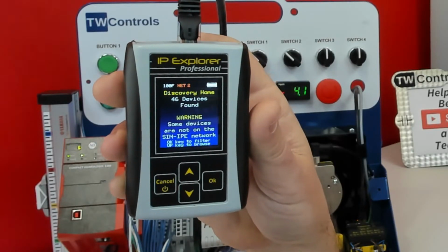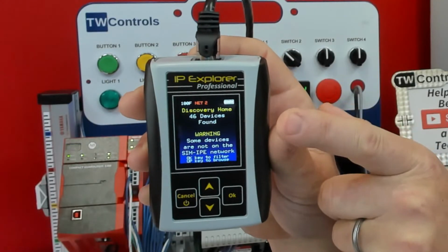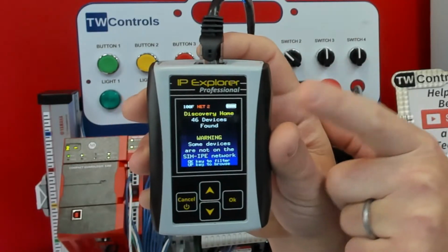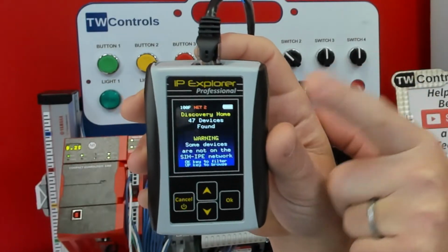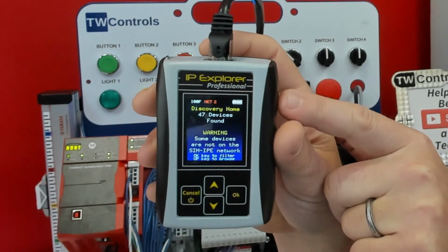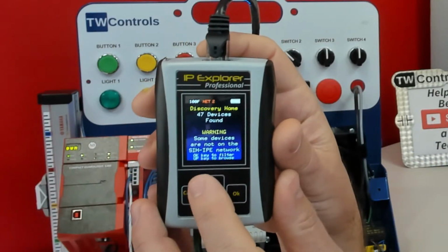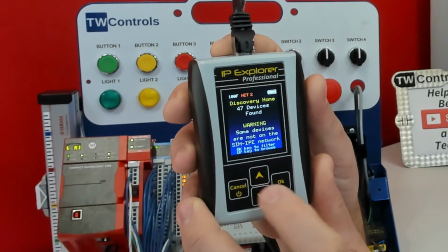Now y'all can see. So whereas FactoryTalk Linx and RsLinx do Ethernet IP, this actually does Ethernet IP, and it also listens for Profinet and GigE and does a few other things to help you discover devices. So it's discovered 47 devices out on the network. And so, yeah, let's just take a moment to go through them.